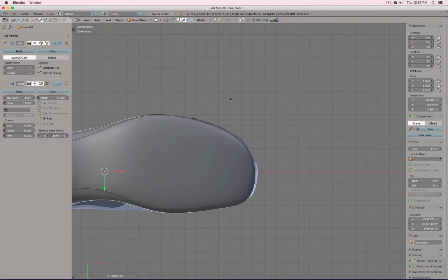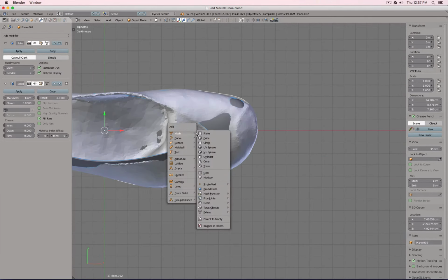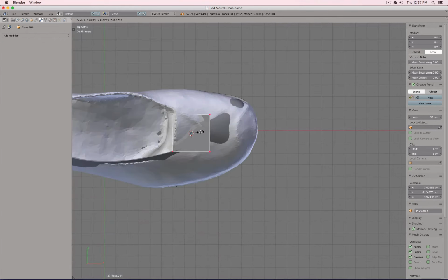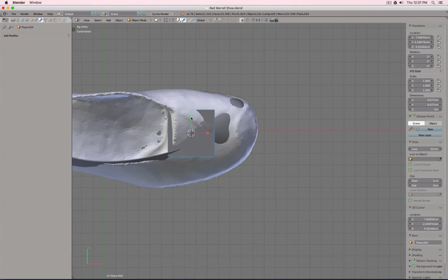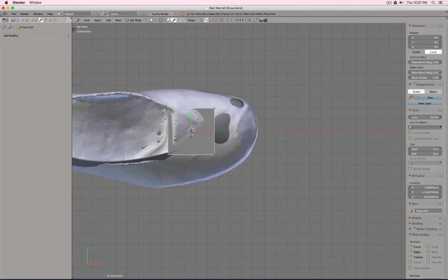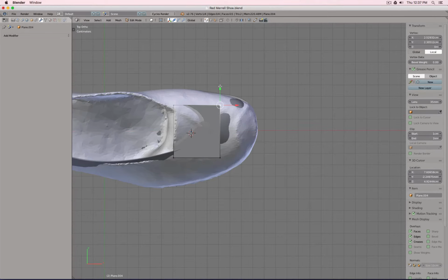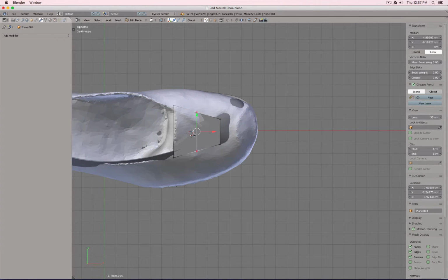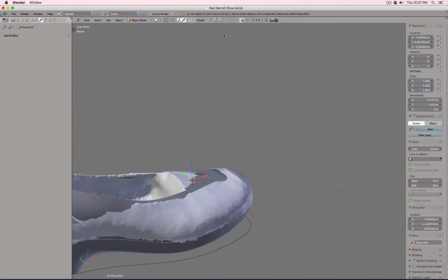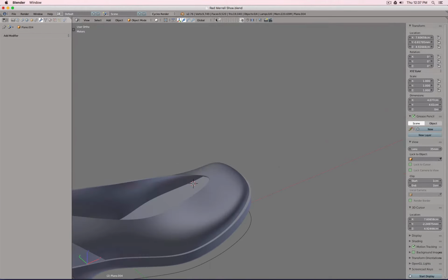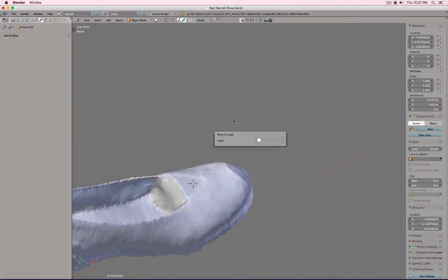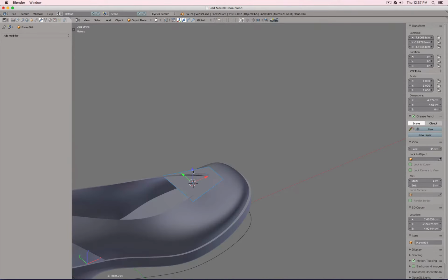Not really difficult. So we're going to top view. I will add another plane, make it really small, a little bit wider or taller than needed. There. So the thing roughly sits here. I think we can move this one in, maybe a loop cut, 2 loop cuts there, and oh, whoops, wrong layer, M and 3 there.